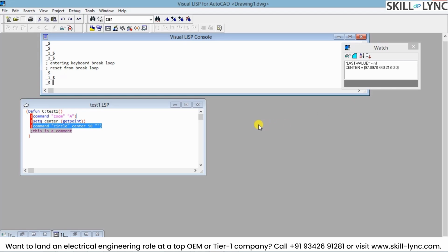So this is, in short, putting together the functionality of the Lisp console to systematically verify each part of your code one by one using the debug command, watch command, and toggle breakpoint command, so that you can thoroughly investigate what the problematic steps are.